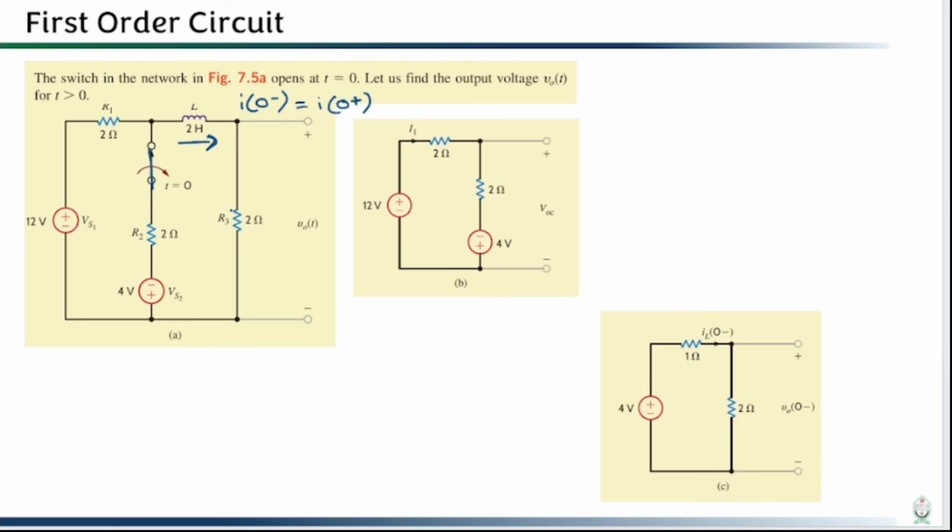So the setup is a bit complex. To make it simple, we can think of another method that we have encountered in our basic circuit course. That is, we can convert it into a Thevenin network looking from these two nodes. If we convert it into a Thevenin network looking from these two nodes, that will give us the load resistor connected here, 2 ohm, and here we will have a very simple Thevenin resistance, and we will have a very simple Thevenin voltage.